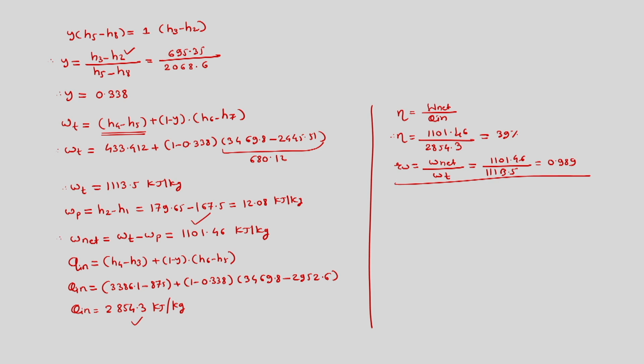So we have to keep this point in mind. We solved this example of drain cascade backward, specifically for the concept where the steam bled out is taken back to the condenser or maybe to the lower pressure feed water heater. So we end the example over here.